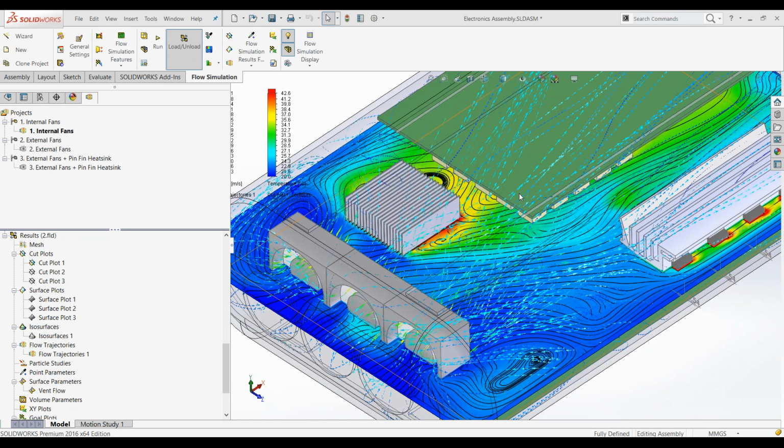Tuning the mesh will help the convergence, but tuning the mesh is more for getting more reliable results rather than getting convergence. The convergence is related to your boundary condition setup, including the temperatures, the heat source, the fans, and so forth. And the goals that you assign to serve as a reference for convergence will also help.